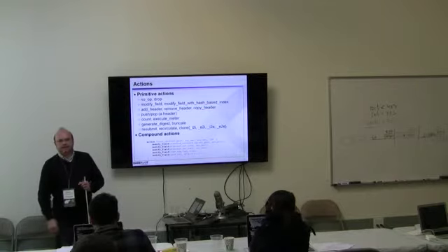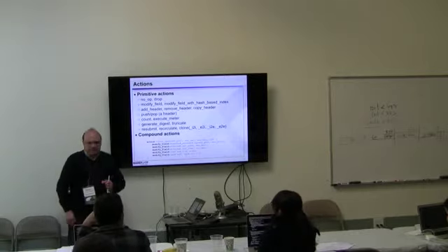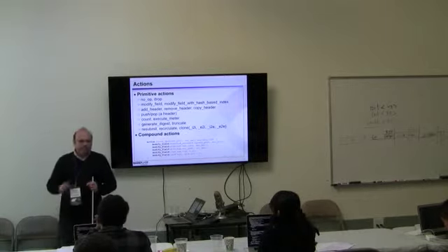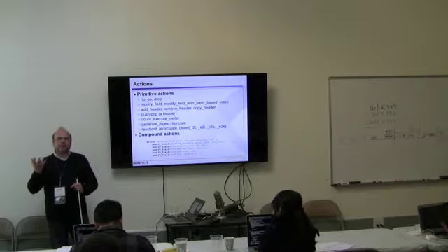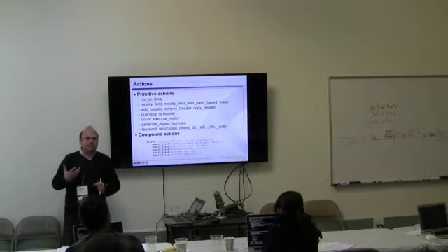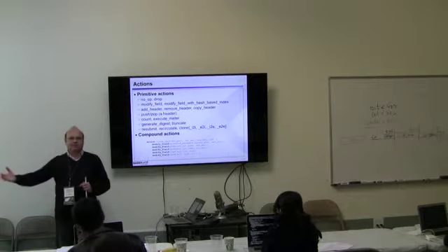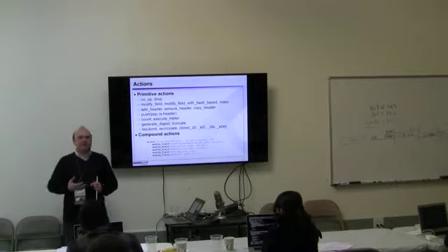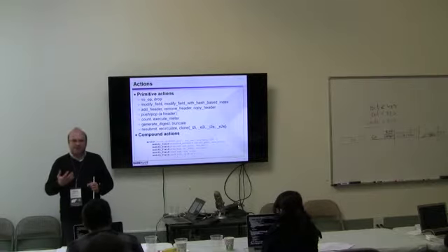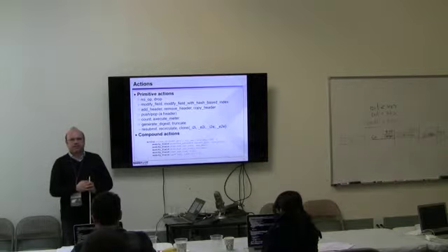I don't see a way to send the packet to the CPU. That's a very good question. In P4, there is really no particular concept of a CPU port per se. What happens is on your target, you can say my port number 0, or 64, or 512, whatever you like, is the CPU port. So it's usually target specific, and that's the number that you just know is the one to the CPU.